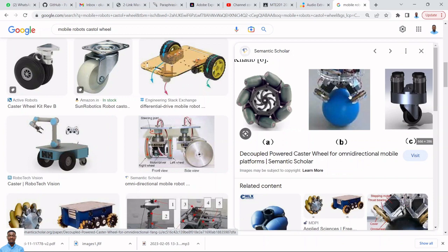This is an omnidirectional kind of wheel. Also, this one, your Mecanum wheel or Swedish 45, is equally omnidirectional. So the rollers are spinning. There's also rotation about the motorized axle and also about the ground contact points here. So this is the ball wheel. This is the castor kind of wheel.